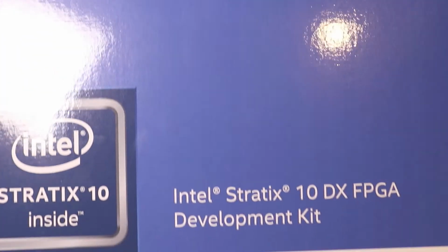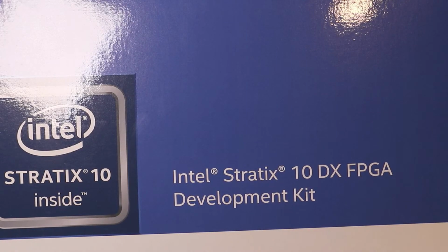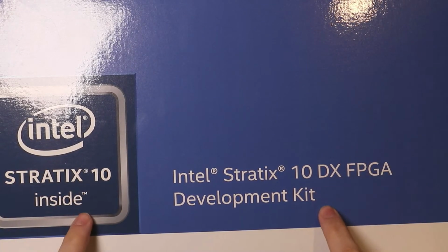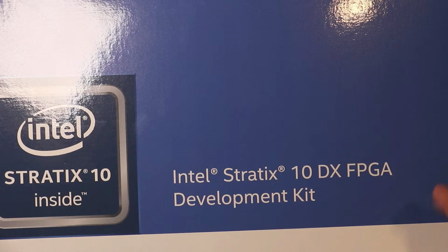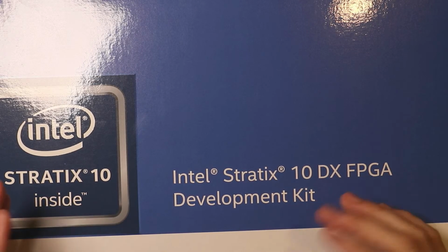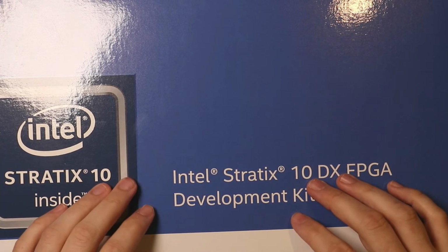I've gotten quite a bit of support from both Intel and Xilinx in terms of getting Corundum up and running. Xilinx has donated a whole bunch of Alveo boards, and recently we requested a couple of boards from Intel. So what we're going to do today is an unboxing of a couple of these dev boards from Intel, and then I'm going to bring up the QSFP interfaces at 10 gigabits per second, and we can take a look at what's involved in getting those serializers working on the Intel FPGAs. And not only that, also some of the debugging tools that are available.